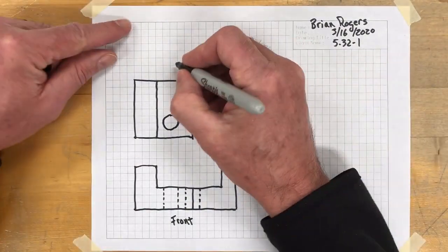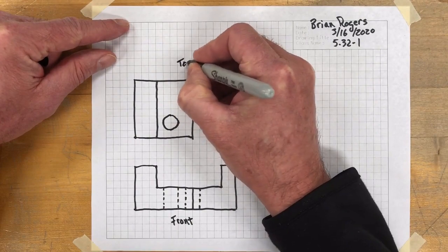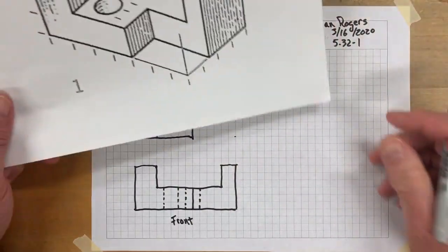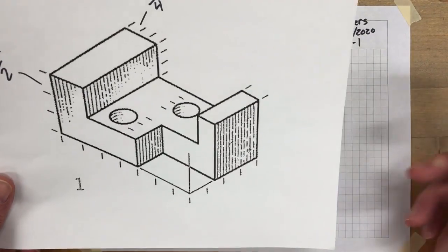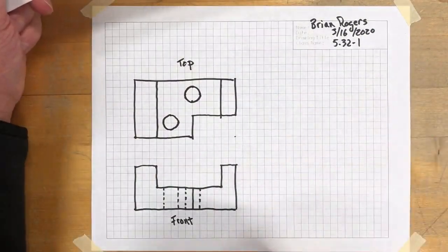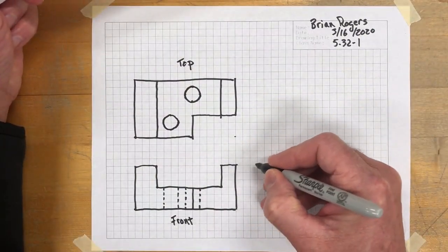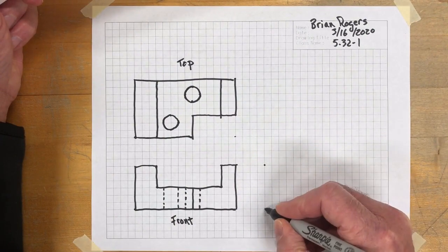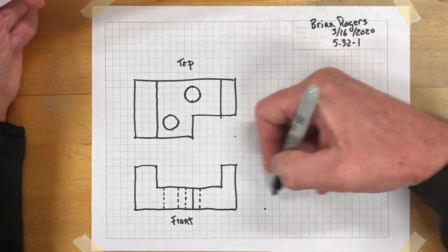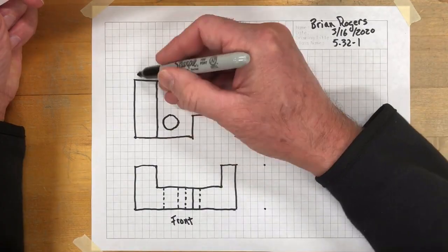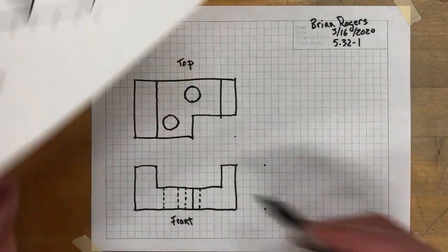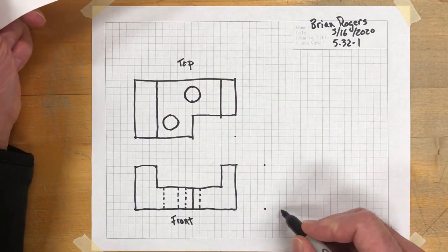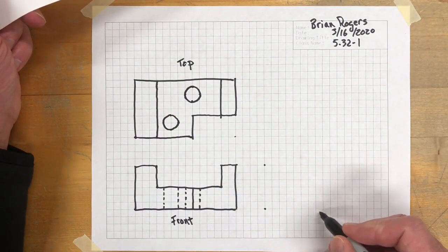That's your top view. Looks pretty good. Now, the right side view. The right side view is if we're taking a look at this object from this direction. So I'm going to get set up with a couple of dots: 1, 2, 3, 4. Same way here. I already know the depth of the object because I described it already. Looking back on this, it's 8 units back, just like it is right here. So 1, 2, 3, 4, 5, 6, 7, 8.